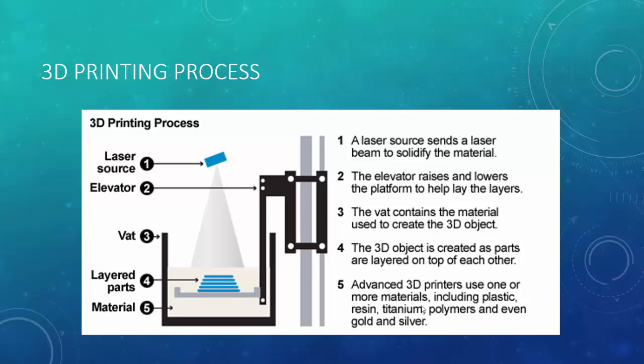3D printing process. A large number of additive processes are now available. The main differences between processes are in the way layers are deposited to create parts and in the materials that are used. Some methods melt or soften material to produce the layers, for example selective laser melting or direct metal laser sintering, while others cure liquid materials using different sophisticated technologies, for example stereolithography.